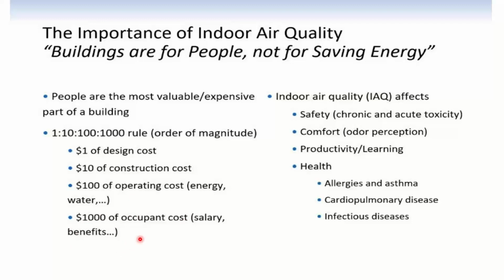So if you do things to penny pinch and save energy, or worse, you do things to build the building cheaper to save first cost, that are then much harder to fix later, more expensive to fix later, you're doing it at the cost of the people. So for example, you size the equipment wrong, you don't put enough staging in, whatever it is, and now you can't really dehumidify well, people will find ways to dehumidify. They'll jack the thermostat down to 68 degrees to get the cooling to run longer to dehumidify, which is obviously extremely wasteful from an energy standpoint. But that's what they're going to do.